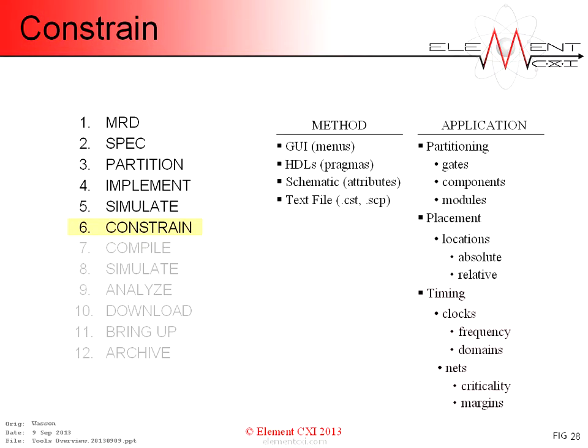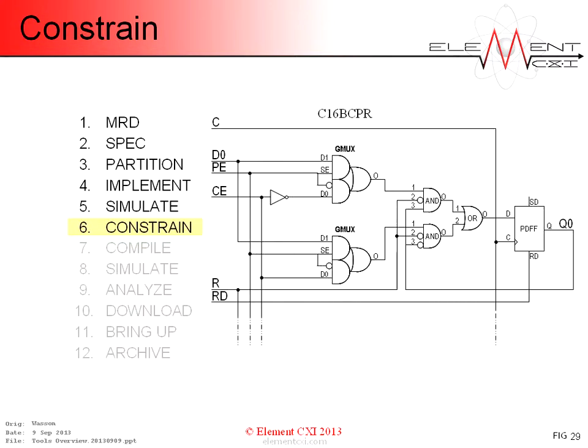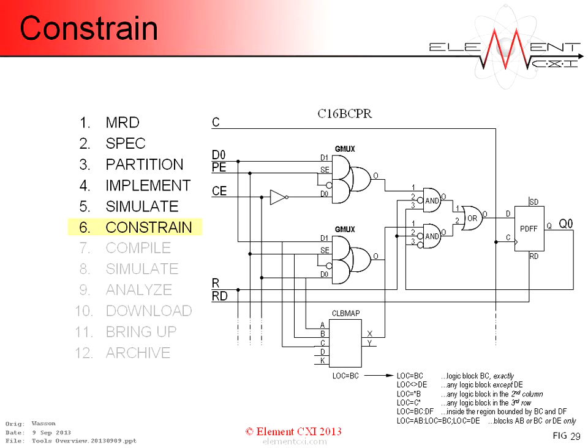The most onerous of these are inapplicable and unnecessary to the CXI architecture. But let's look at them anyway to see what the typical FPGA user assumes is required. Schematics have offered the very lowest level control. For example, combinatorial logic can be mapped, partitioned, together into a common LUT. That block's location can be fixed in the logic array exactly, or by exception, in a specific column or row, or within a rectangle or a group. Signals can be locked to specific LUT pins, components can be named, and nets can have attributes attached to them.